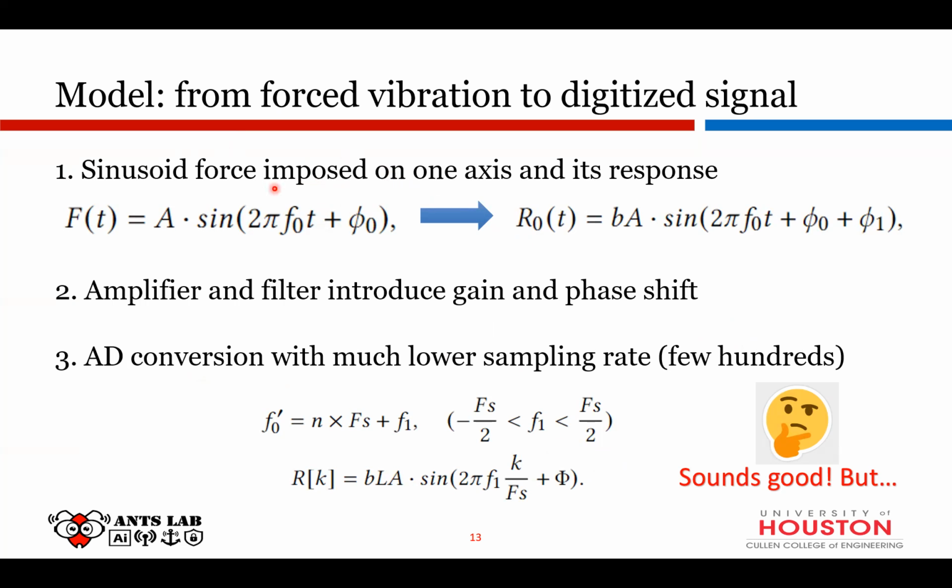And here is the mathematical model behind the relationship between the gyro readings and the ultrasound. Let's say the speaker generates a sinusoid signal, and this sinusoid signal impinges on the chip of the MEMS system on one axis, producing the Coriolis force with some amplitude and some phase.